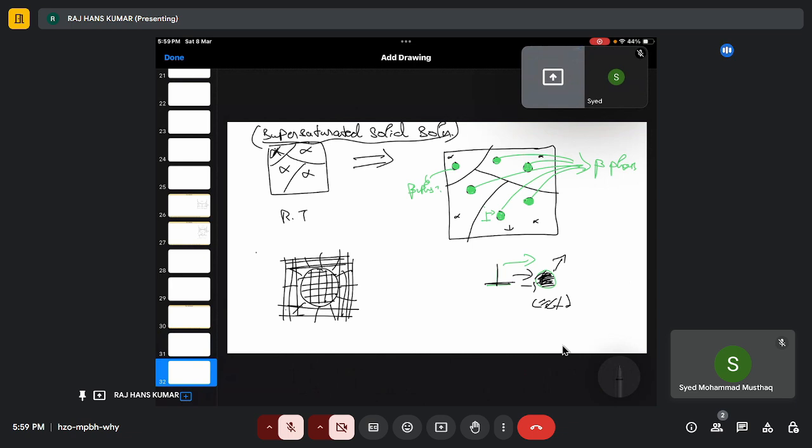There is also straining in atomic length. And around the dislocation, there is also a strain field distribution. And there is also the strain field around this lattice parameter. Because of these two strain fields coming into contact, most of the time the dislocation cannot move further, because these precipitates act as obstacles. These dislocations cannot freely move. That means we are restricting the motion of dislocations.